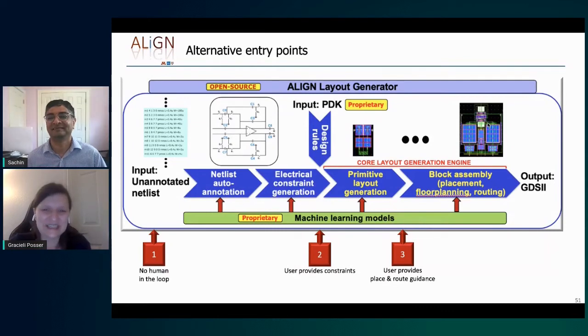That's nice. So another two questions from Sai Sharan. He's from Vardhaman, India. The first question is, how reliable is this automatic flow in terms of DRC and LVS? So not all of our layouts are completely DRC clean, but at least for familiar structures, they are DRC clean or they have a very small number of DRC errors at this point. LVS is generally clean. Yeah, I think LVS you need to be almost completely clean to make it.